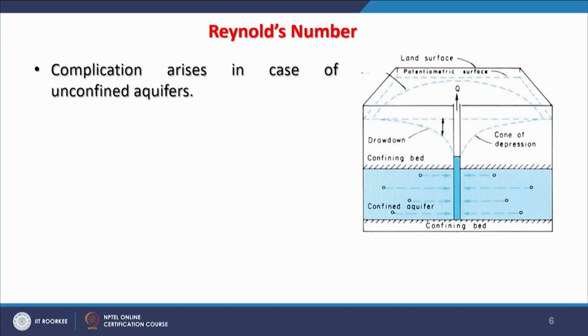So, this is really very important, whatever the formations are, whether it is hard rock like granitic terrain or sedimentary rocks like sandstone, the speed of withdrawal, the Q, should be kept at the optimum. I would not say minimum, but optimum, so that the Reynolds number does not increase and the flow remains laminar towards the well, and therefore the life and health of the well would be much longer.